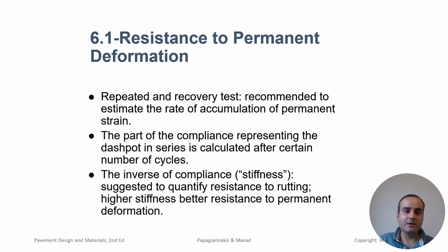accumulates over time. To model this behavior, the dashpot elements in the viscoelastic representation are used to capture the material's time-dependent permanent deformation. The part of the compliance is calculated after a certain number of cycles, providing insight into the material's tendency to accumulate strain under repetitive loads.